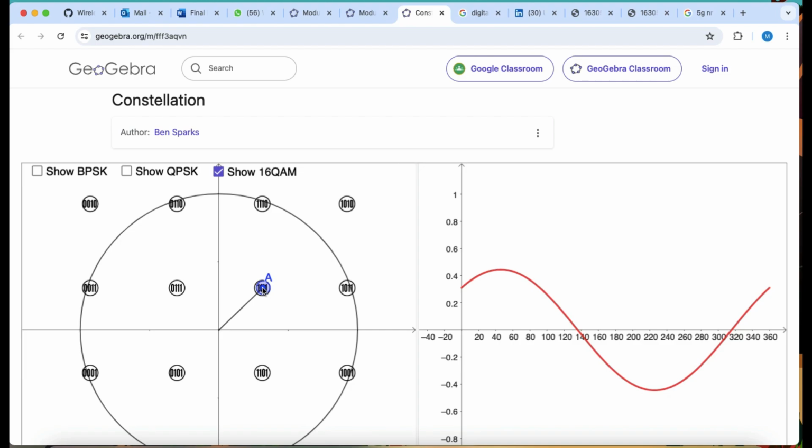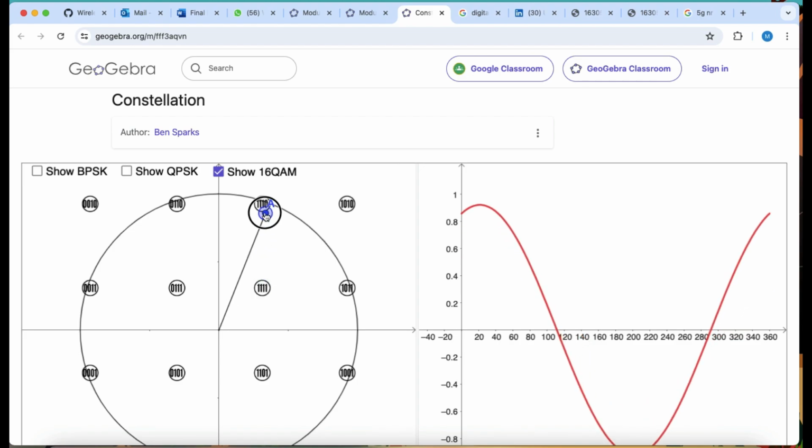But what was the problem that I mentioned when I was doing the simulation in GNU Radio? I mentioned, when these points start increasing, what will happen to it? Whenever the noise is there, it will start corrupting these constellation points. So the higher the modulation scheme is going to be, the more likely noise will be able to corrupt these points. So what is the technique that 5G and these technological components in cellular telephony use? They said, you know what? We're going to use adaptive modulation and coding schemes, which will do what?